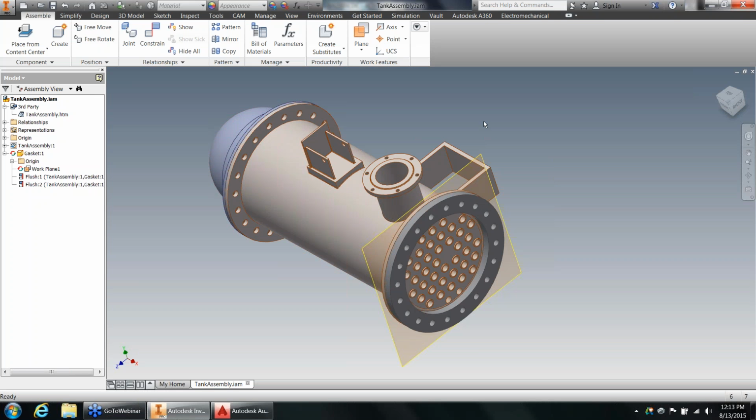All of my other associations that I'd put into this model are still there. In this case, it was a very basic change, just an overall length value that was updated. If, for example, it was a part that got completely swapped out for another part, just like in an Inventor session, those relationships that bind those designs together are obviously going to cause some problems, right? If I take a square part and replace it with a round part in Inventor, I'm going to lose relationship data, constraints and joints and so on. The same sort of thing would hold true here, right? But size change definitions, positional definitions, all of those changes aren't going to really affect your constraints per se. All of that's going to trickle across.